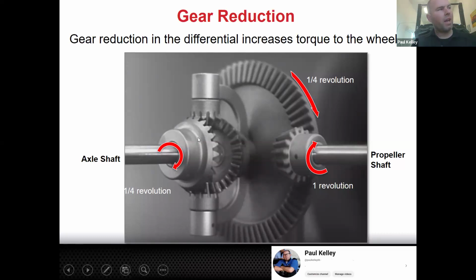So what'll actually happen, we'll call this the side gear, but sometimes people say the spider gear, but the spider gear could mean any one of these gears. So that's why I'll specify. This is a differential side gear. This is a differential pinion gear. This is a pinion. You gotta be kidding me. Yeah, I am. This is a differential pinion, though, not a pinion as part of the ring and pinion.